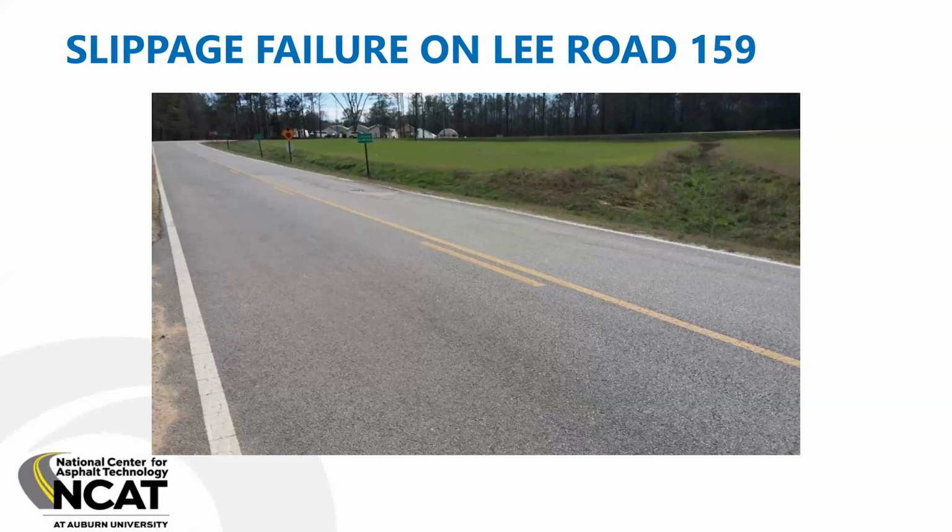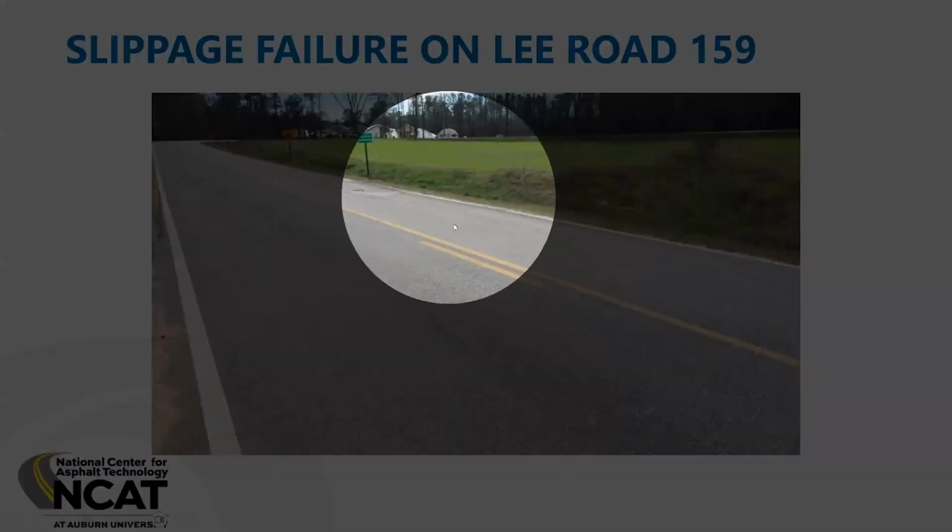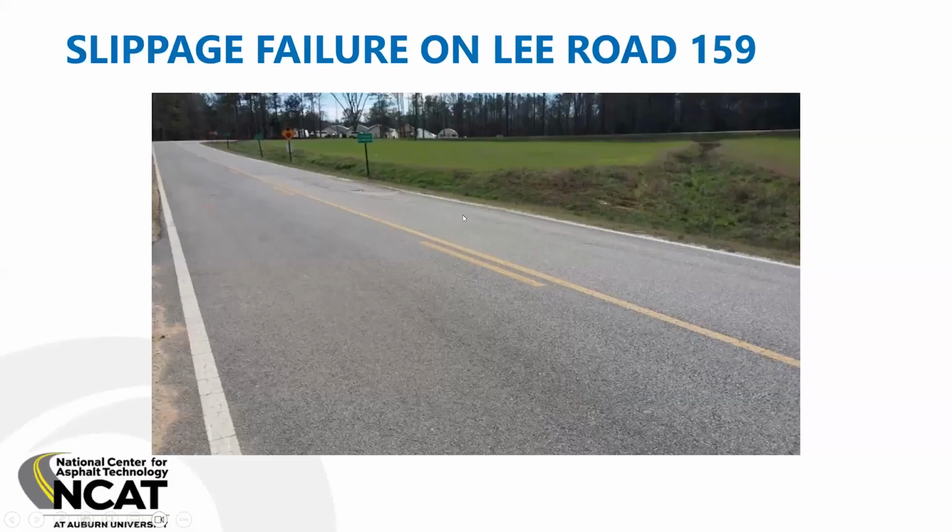We didn't do any crack repairs on any of the thin lay test sections. We just broomed and tacked and paved. So in this one particular test section, we had a slippage failure that occurred, and it was because water got up into the pavement structure through the cracks, got into the tack interface and caused this failure.